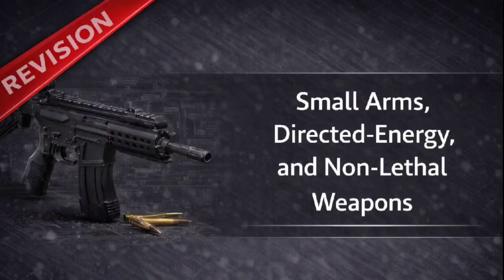A core design feature of the Tavor is the bullpup layout. This radically changes the rifle's silhouette. How does locating the mechanism behind the trigger offer such a great advantage? The bullpup configuration places the magazine and the entire firing mechanism behind the trigger group. The primary advantage is length reduction. The weapon achieves a 30% shorter overall length while, and this is critical, retaining the full, long barrel length.